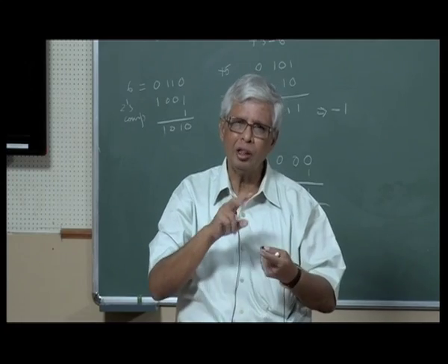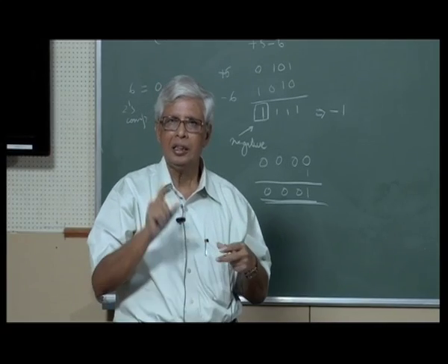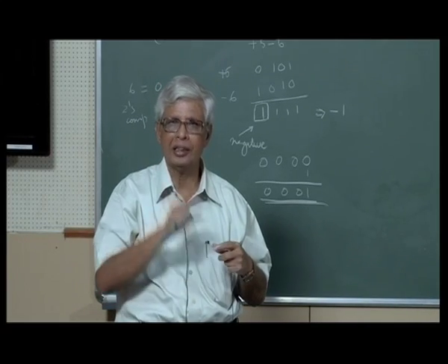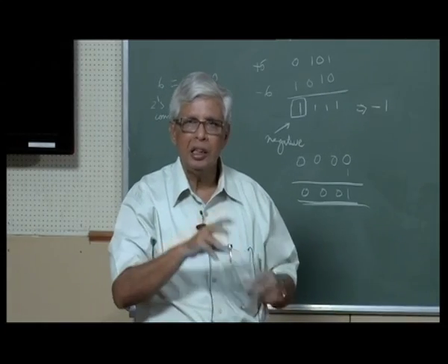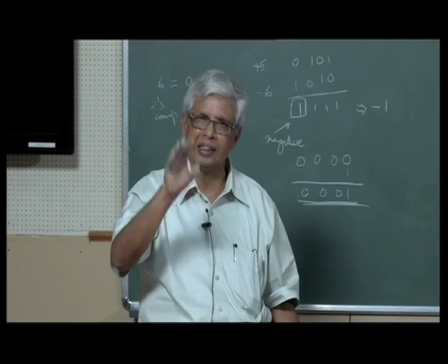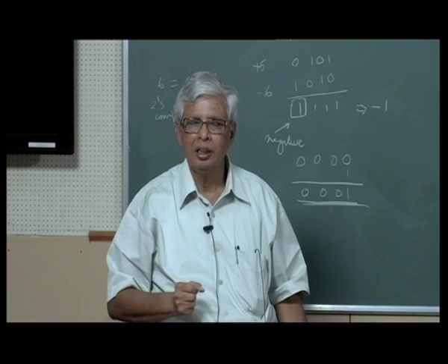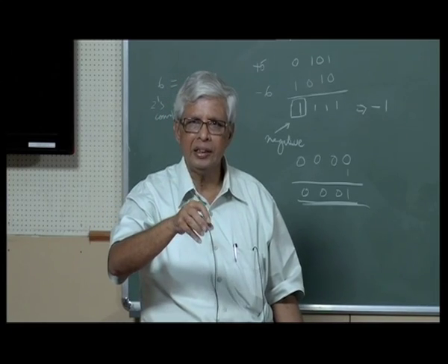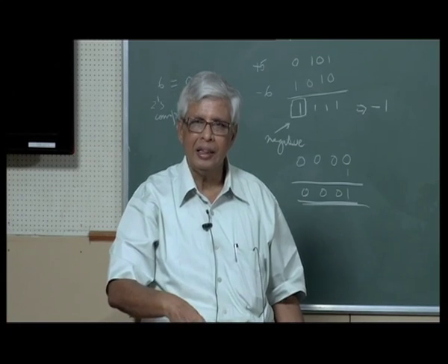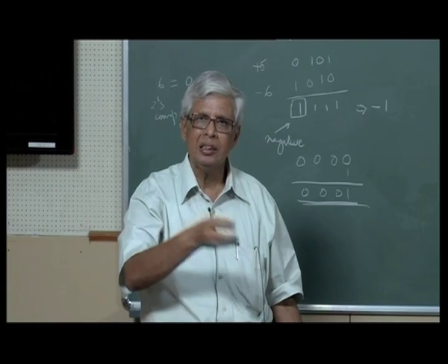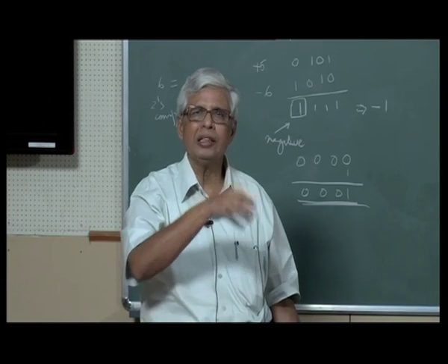first of all, I will explain why you want to add or subtract using complement numbers. In design of arithmetic logic units, in calculators, in computers, they cannot have too much hardware. Your arithmetic logic unit can deal with addition. If you want to build a subtractor, that is again another job. So they want to have one unit which adds and the same unit to be used for subtraction. That is why they have thought of this 2's complement or 1's complement, so that subtraction will be same as addition.